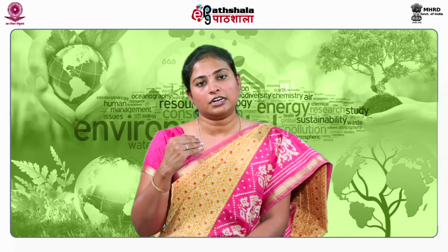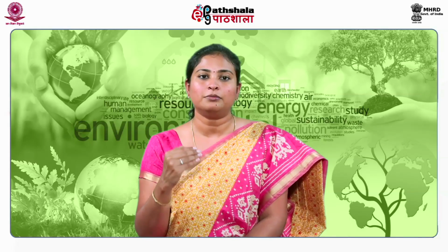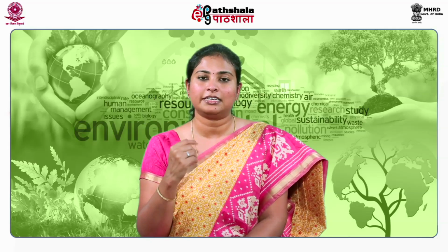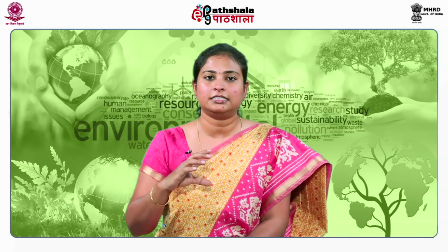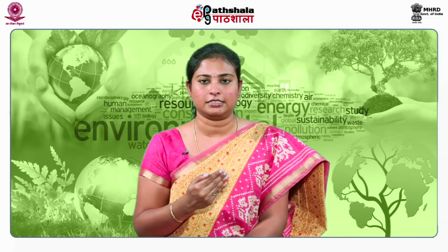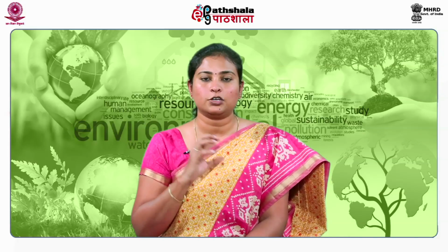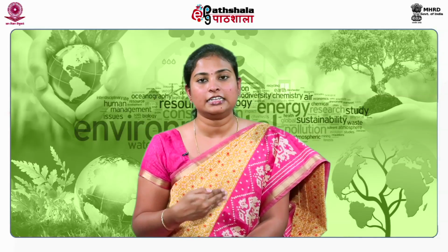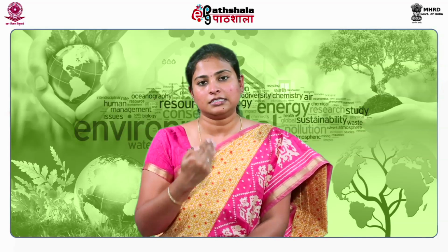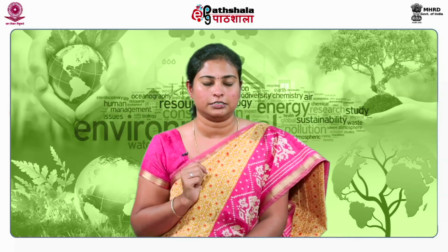Then you have to continuously monitor the waste density and settlement. The rate of degradation and waste saturation are determined from waste density monitoring. Monitoring of settlement on the surface of the landfill bioreactor might help in calculating the available space in each cell of the landfill bioreactor. This will also facilitate more loading of waste. Then you should continuously monitor gas flow and quality, because the quality and quantity of gas generation will again indicate the biological activity going on inside the landfill bioreactor, and this information will also be required for expansion of the plan and modification of gas management systems.